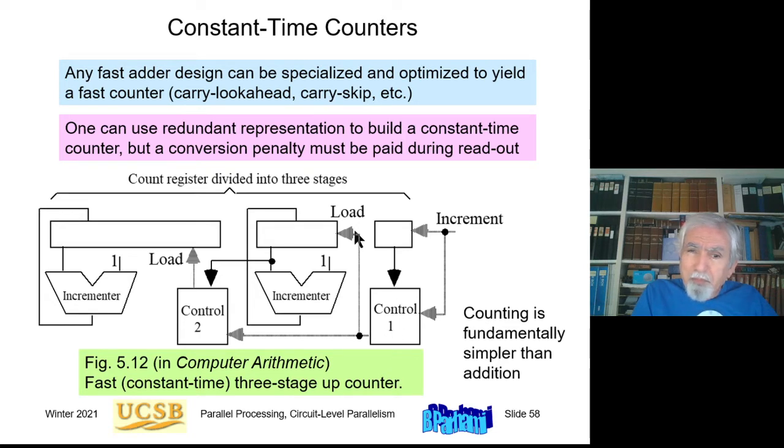And however, instead of incrementing this one, which would take more time given that it's wider, I pre-compute the incremented value during the time when this one is doing its job, during these, let's say, 8 clock cycles, where this one is being incremented and it doesn't generate a signal to increment this part.